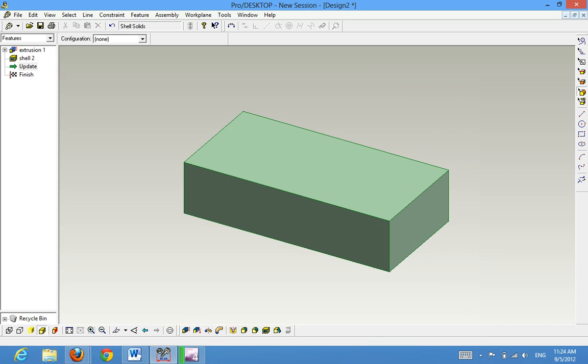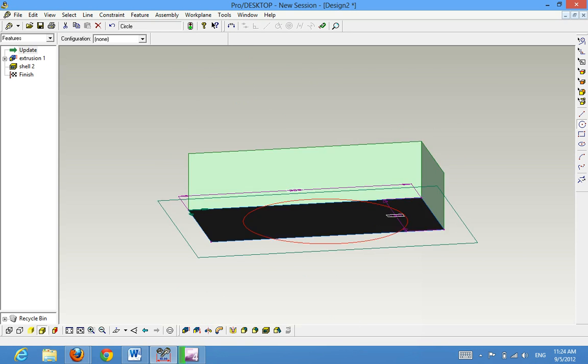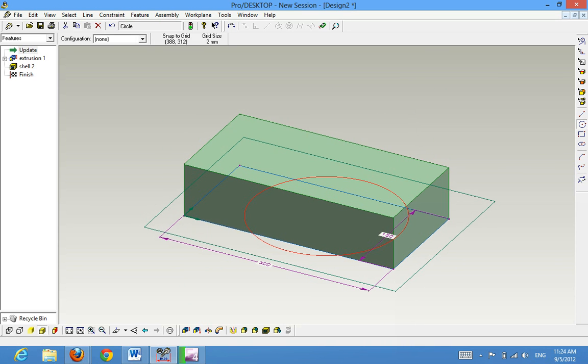Next part of the process is to build a sound hole. So I want to select the top face, which is where I want my sound hole. I'm just going to create a work plane now. This is a step that people often forget and they end up sketching again on the base. So if I just start to draw now, I'll actually wreck the whole thing, okay, because I've sketched back down on the base profile. And that's not where I want to do it. So don't do that, I'll just delete that out.